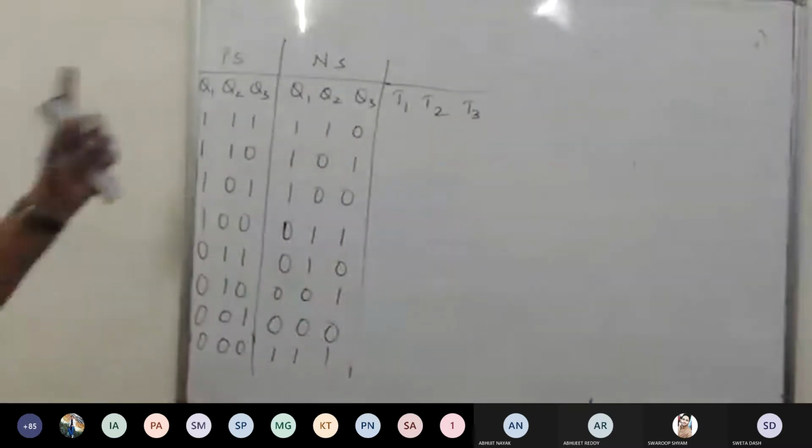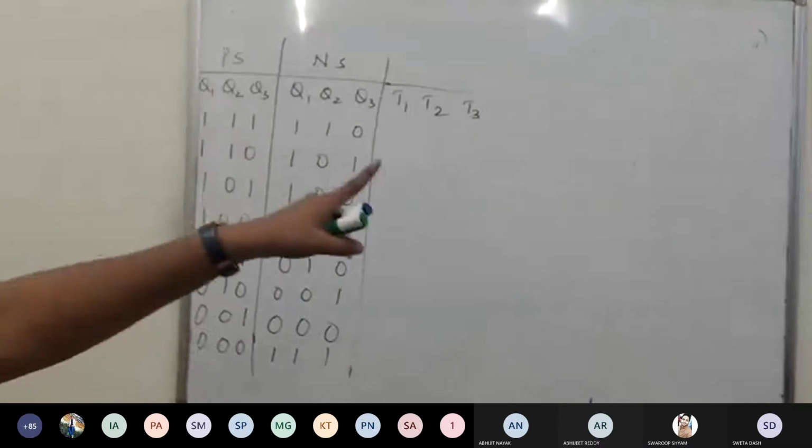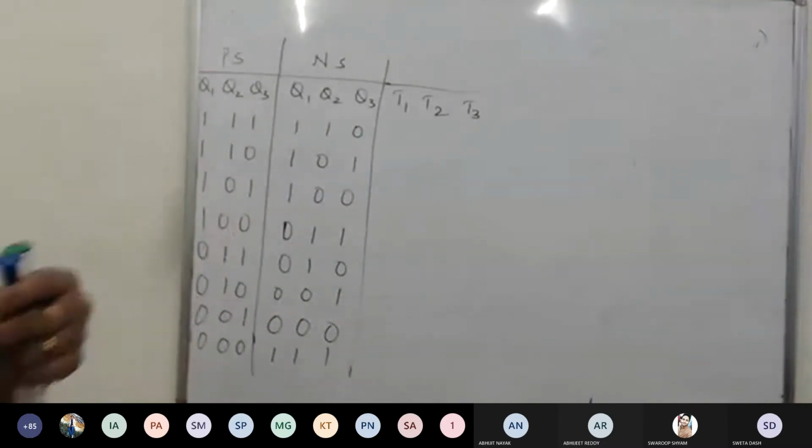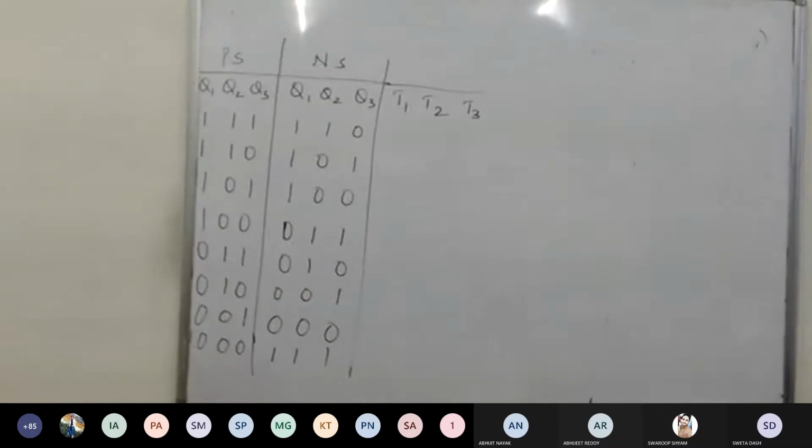How it looks. You have an up counter, you have a down counter. Already the up counter is done. Right now this is a down counter. Now relate those two circuits. Do you find any difference in that? That's all. I only need that much answer. Once you finish it, because I'm continuously using only the T flip-flops, I don't think you will have much difficulty in that.